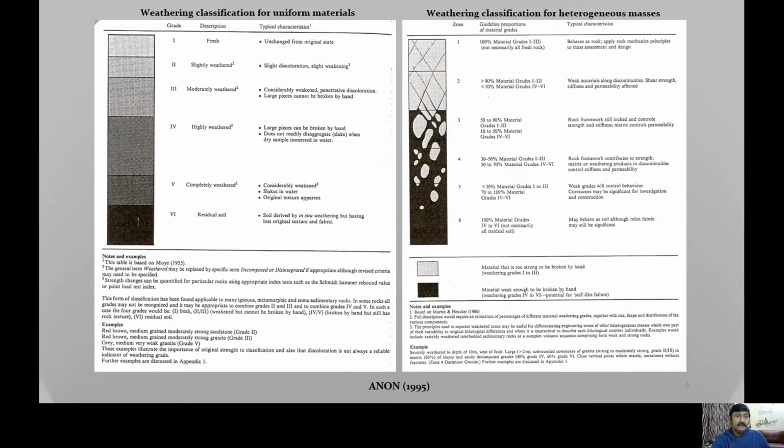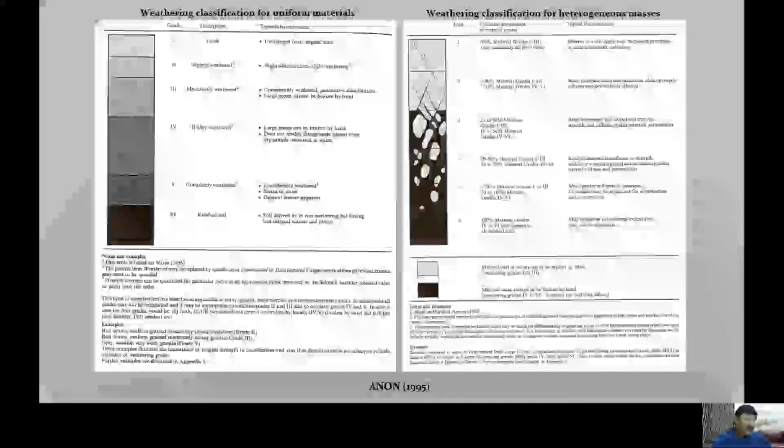When we look at this common six-fold weathering classification, it should be remembered that this particular classification is purely based on chemical weathering processes, or on the manifestation of chemical weathering processes. It does not specifically take care of the manifestations of physical weathering processes, and therefore this gradational change is possible to be captured through this classification system.